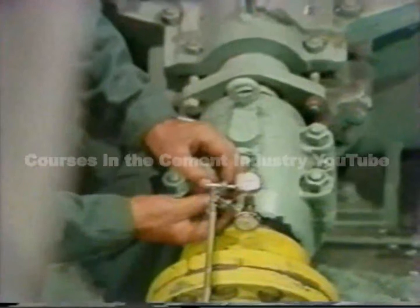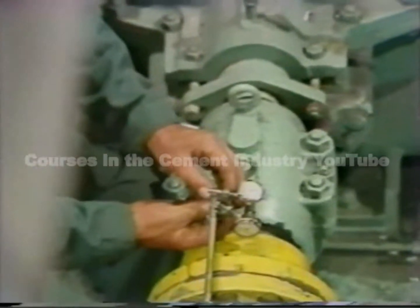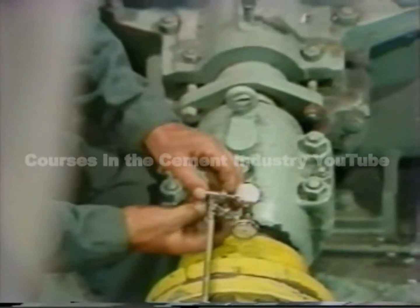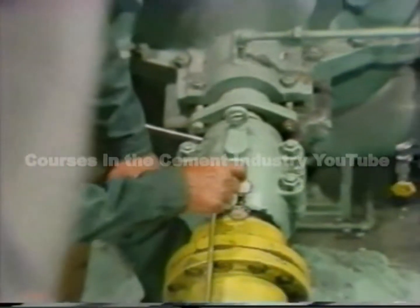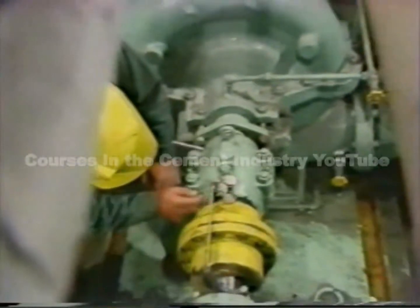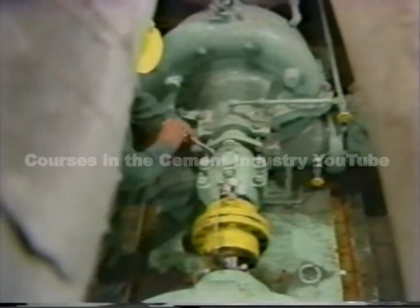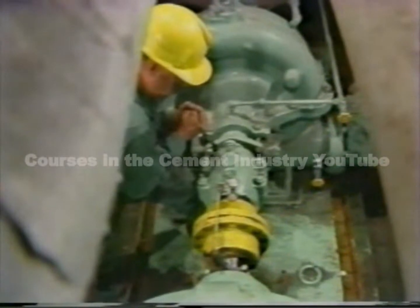What I do want you to remember now is that angular misalignment is detected by measuring variations in the distance between the coupling halves. In the example we saw, vertical angular was shown. Horizontal angular is detected in the same way, except you look for variations in distance from one side to the other rather than from top to bottom.